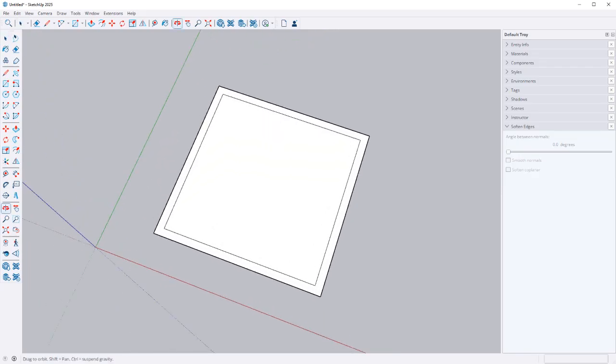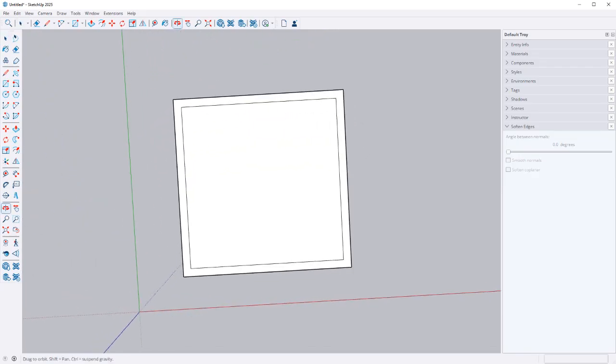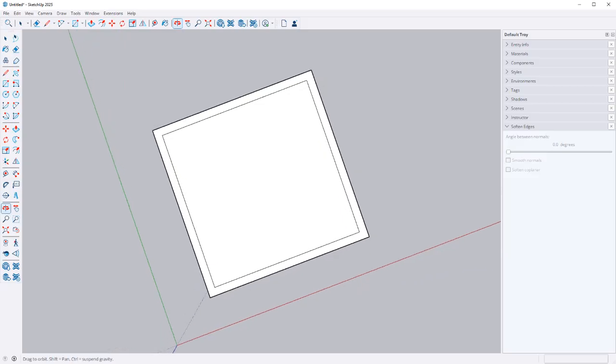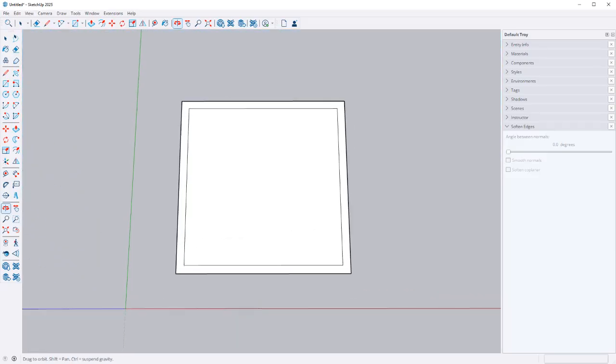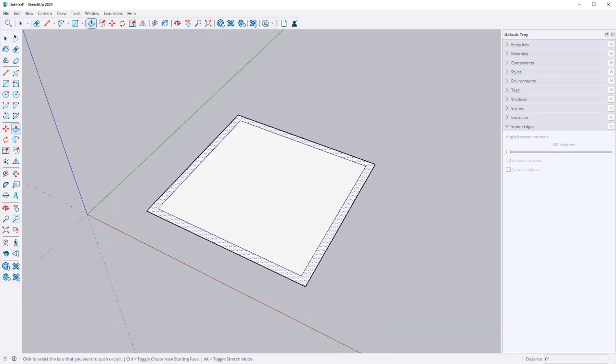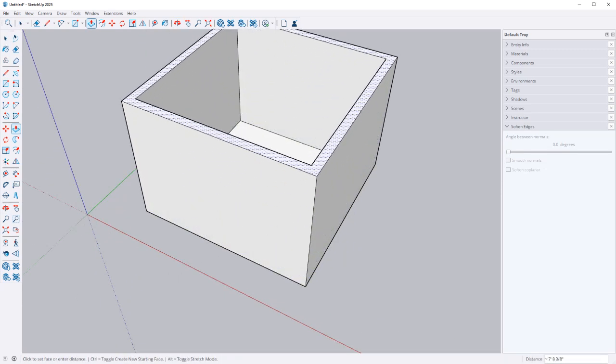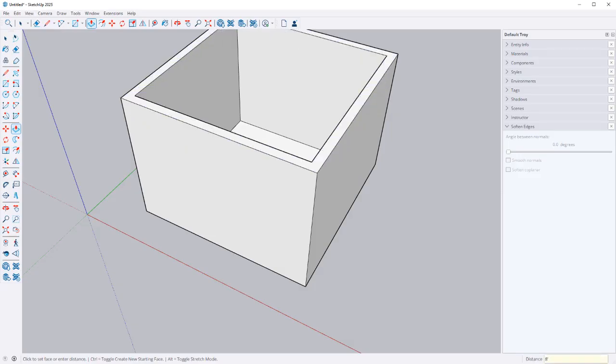If you want to think of what we're doing in AutoCAD, just look at it from top down, right? We've got this 10 by 10 border we created, just like we would have done with AutoCAD. We offset those lines out here, so we have the exterior walls we're working with. And then to actually turn these into walls visually, what we'll use is the push-pull tool, and we'll pull these walls up. And we'll do 8 feet, and that'll set the height for them.